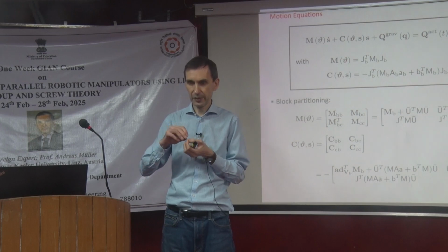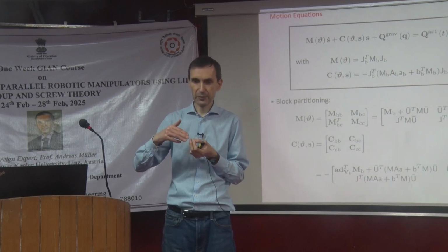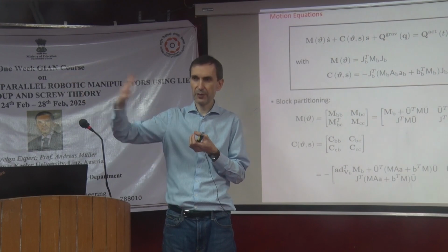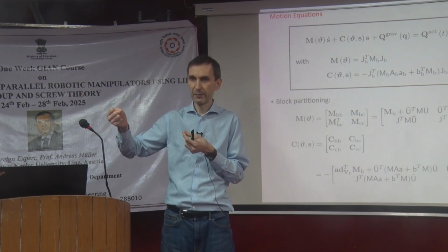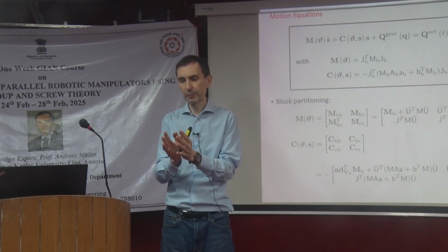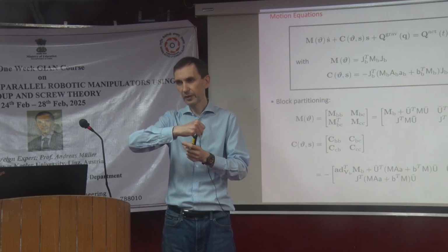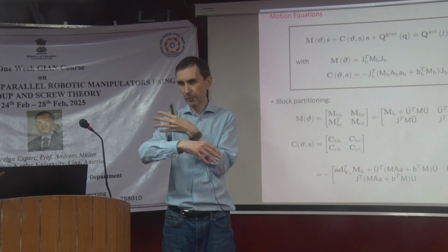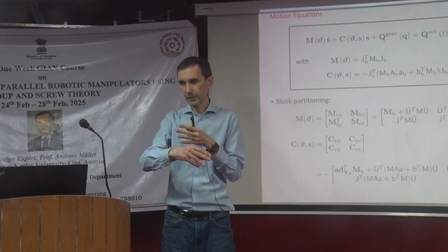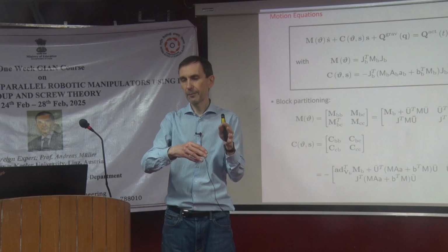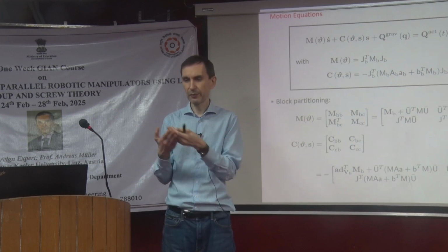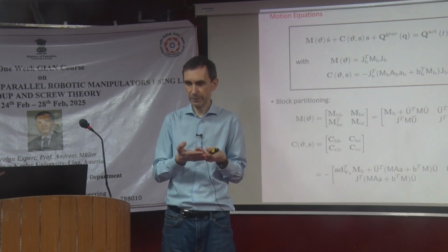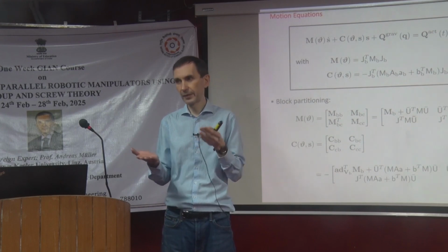Because then, as I was saying, you measure the transfer function by assuming a linear model. At every state of the system, at every pose of the robot, the robot is fixed. The only thing that you're measuring is the transfer function due to the linear model that consists of the mass and the damping and the stiffness, which are linear.